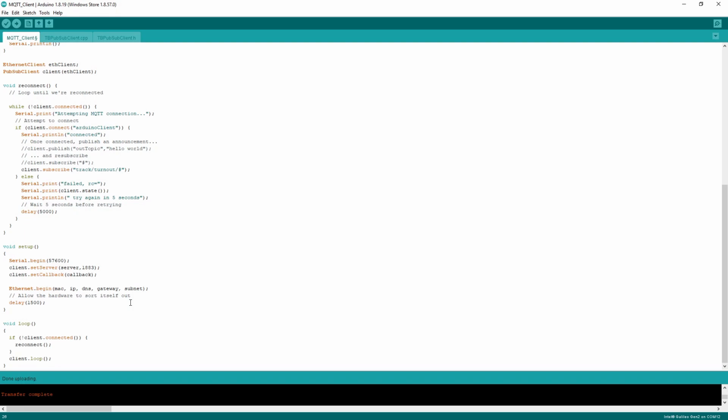So I went and got myself an Arduino library and I configured it and I set it off, and I couldn't receive any messages. Now I think it's because the Ethernet setup on this script is only allowing the Arduino access to my local network and not to the internet. And I haven't quite got to the bottom of why, and I think it would at this point be a bit of a waste of time to find out why, because I'm only trying to connect to a test server.